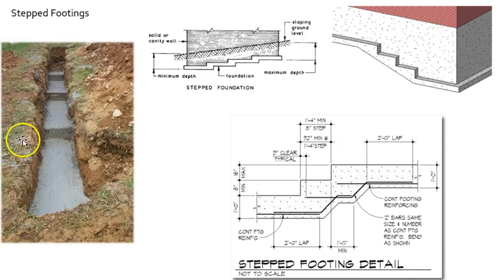And as we just discussed soil types, this one clearly has been dug out. This is probably the exact depth of the backhoe bucket, and it was just dug out. So the soil type, a clay-like soil, something very sturdy that would stand up. The soil type plus the municipality would allow, and the structural engineer, those three components really, the municipality, the structural engineer who designed it, plus the soil being as stable as it is, allows the contractor to just use the bucket for the backhoe and just dig this out.